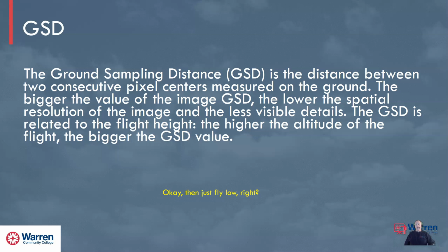So maybe higher. Sometimes you can capture more area with higher. So if my geographic area is huge, and I'm flying a quadcopter that can only do a certain amount on a battery, you can be out there for days doing this. So if you go higher, you might get done faster and you might cover a larger geography. So it really does come down to what you're trying to do.